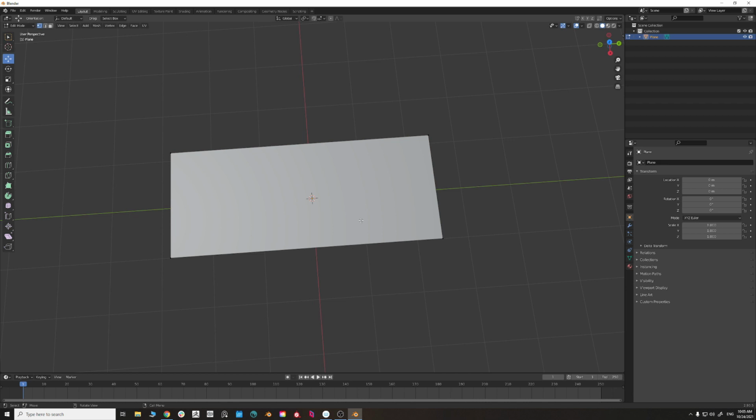And what I would like to have right here is a bit of a junction. I'm going to do that by using the loop cut. I'm going to position it where I want the junction to be, somewhere like over here, perhaps. Yeah, over here is good. And then I'm going to go to edge mode over here. Just for a second, I'm going to need to drop the loop cut tool. I'm going to use the select box to drop it. Yeah. I'm going to select this edge right here.